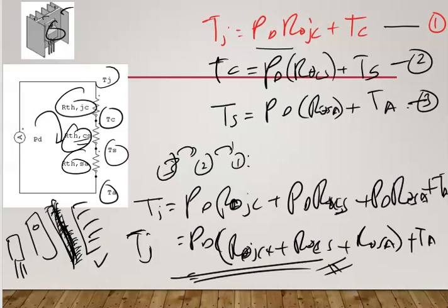Thermal paste has its own material thermal resistance, and at the back of the black plastic encapsulation your silicon dies have a metal tap. This metal tap will be attached to the heatsink through this thermal layer or thermal paste, and also the metal tap will attach to your plastic case here.